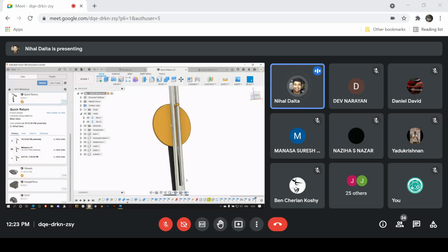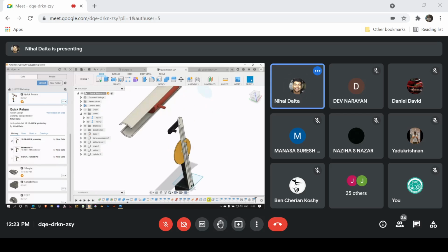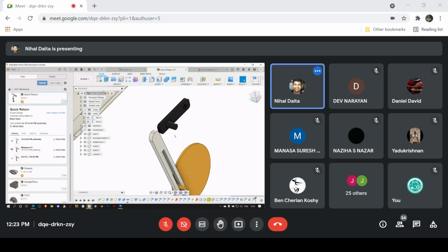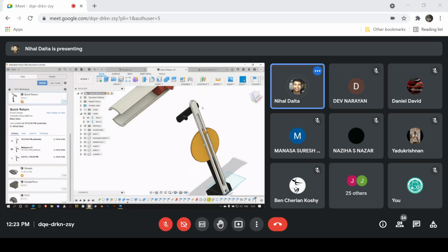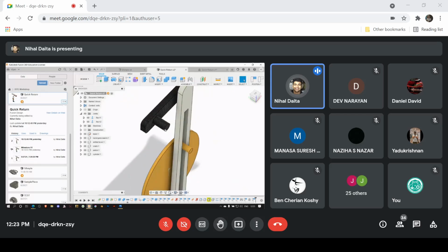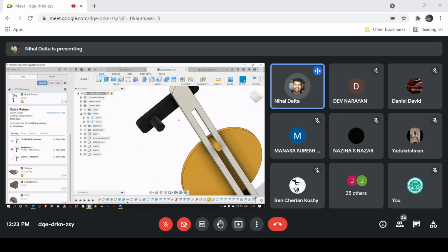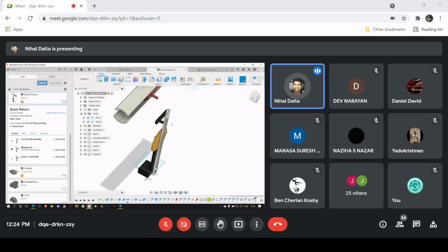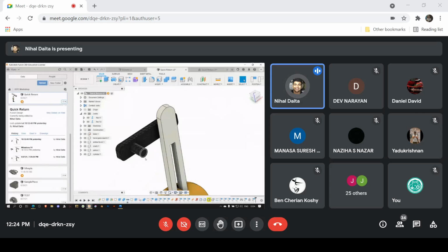Okay, for some reason I'm missing something. I don't know why, but it seems to be missing a certain slot, I guess. I don't know what happened. Let me just quickly play. Yeah, this is another important or easy use when it comes to Fusion, right? When you are working with assemblies, you can pretty easily make corrections. So yeah, this is another easy tool. You see this inspect one, right? I just click that and click this one. It gives me all the information I need. It's a radius 1.5 or diameter 3. So I need to create a slot here.